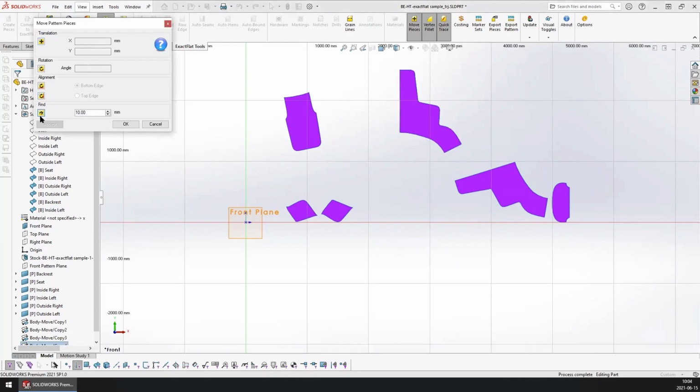And our last tool is our Find tool. This tool is used to find neighboring pattern pieces. We can set an optional offset here. I like to give myself a lot of extra material, so I'm going to change this to 300 millimeters to give myself a lot of space. When I click on an edge, again, I'm going to click and hold. We have our preview on the left-hand side, and we also have a green dot appearing on that edge.